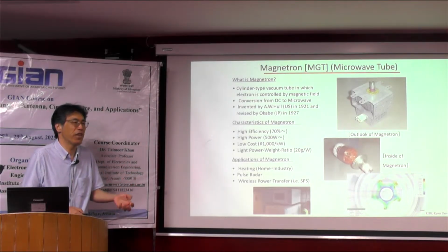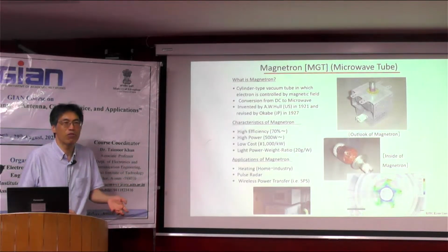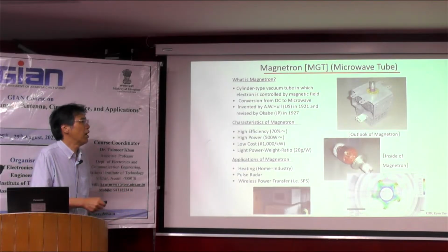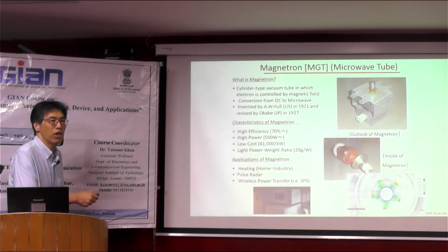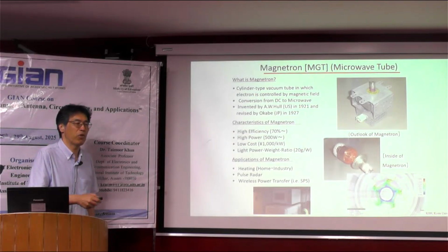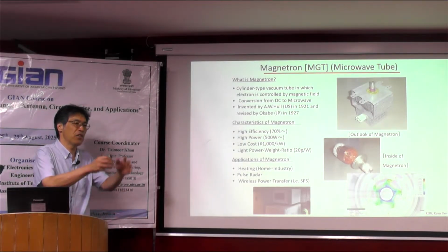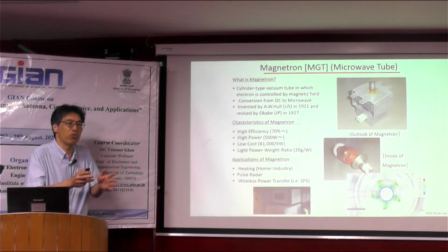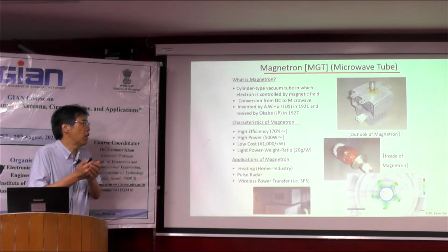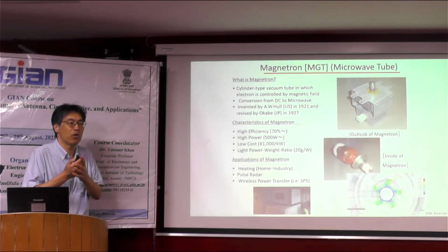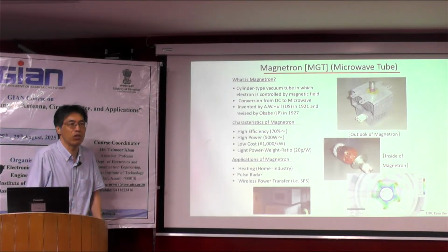But recently, they all use semiconductors. But still, for the microwave oven, we use the magnetron. And for broadcasting from the satellite, the satellite has a microwave tube, a traveling wave tube (TWT), and they transmit the wireless communication radio wave from space to the ground.